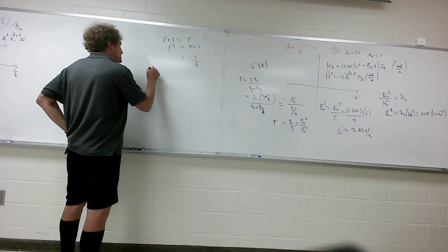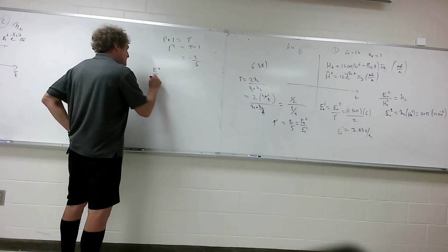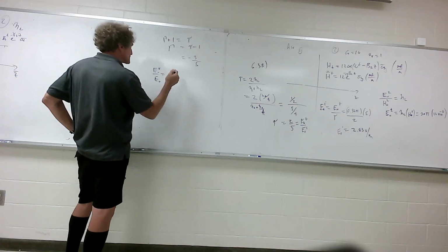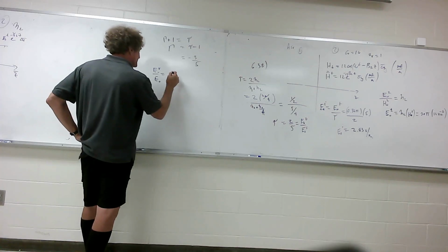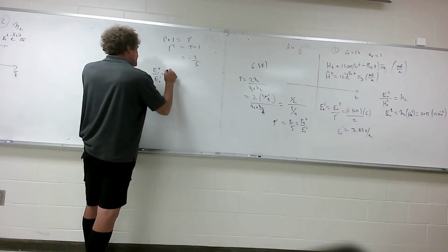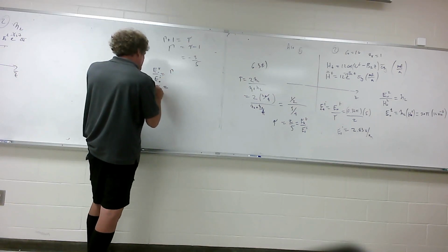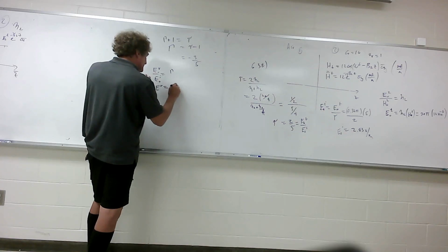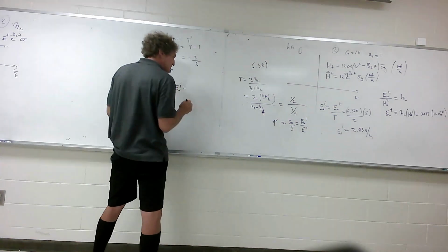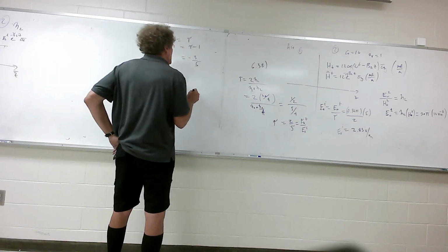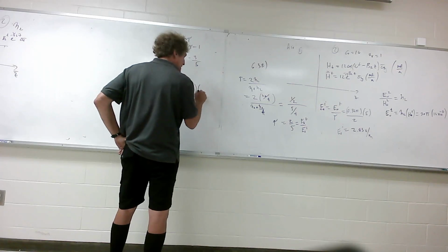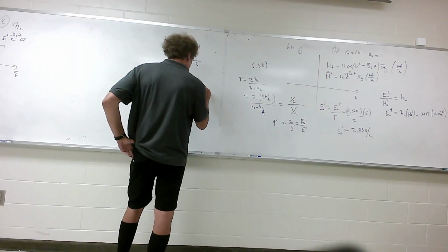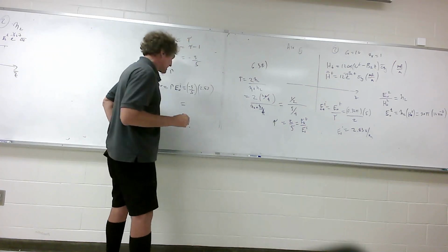That means the actual value of the reflected field, this is going to be just the magnitude, the actual value of the coefficient, which is going to be a real number. So the reflected field itself is the reflection coefficient times the incident field. The reflection coefficient is minus 3/5 times the incident field, which is 2.83. And what's that come down to?